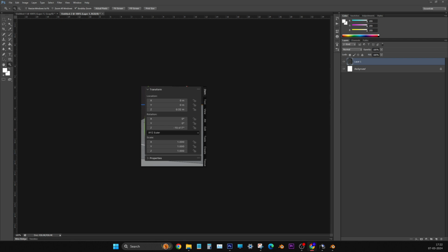Right. Now you just go back, just go to tab. There is edit mode, component mode. Keeping the cursor in the viewport, go to component mode. Edit. Right. Now it is all selected. You know that in Blender now, by default, when you enter edit mode, all vertices, faces, edges will be selected. That is why it is showing in yellow color.